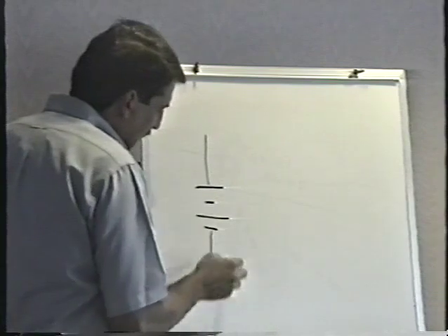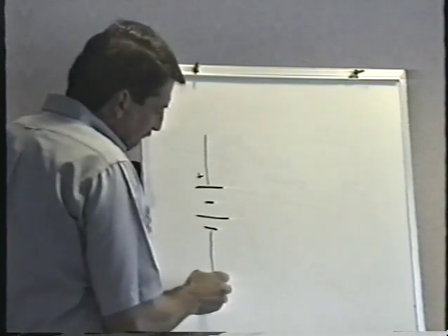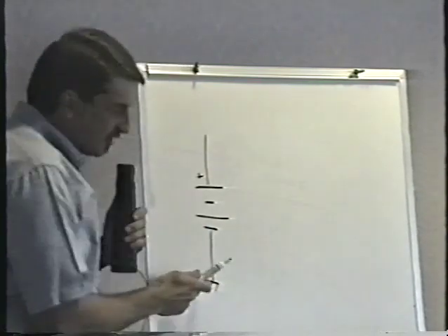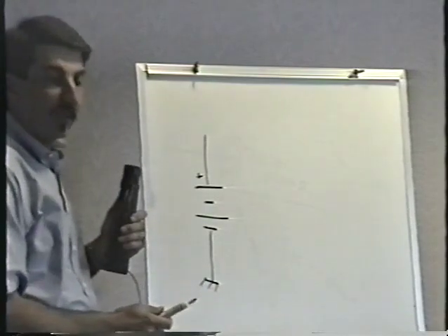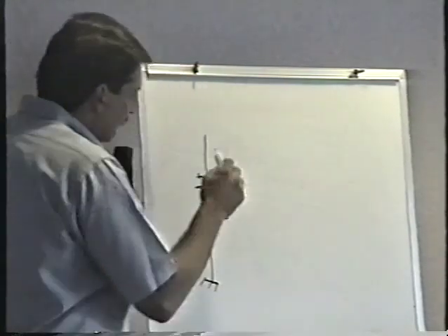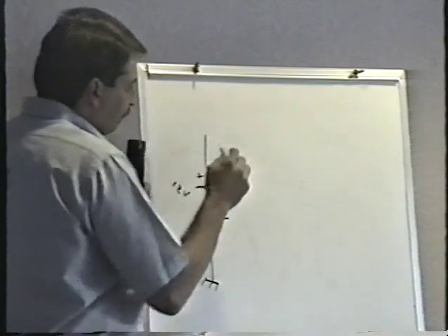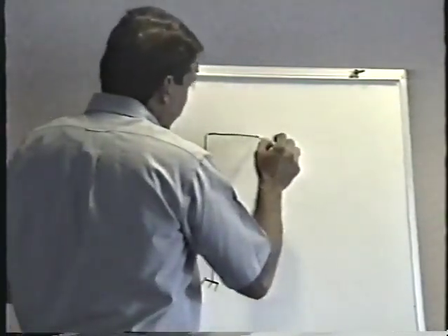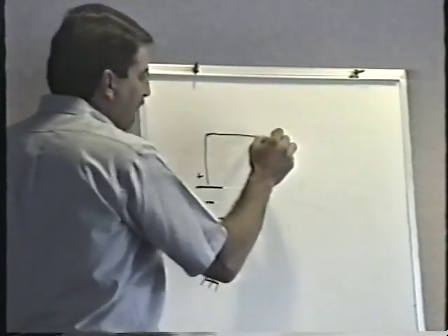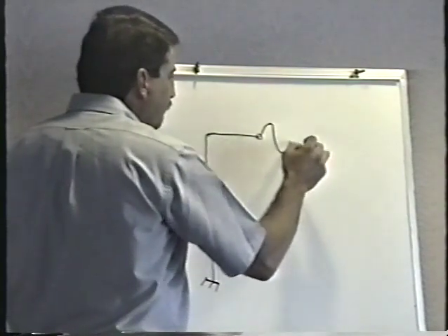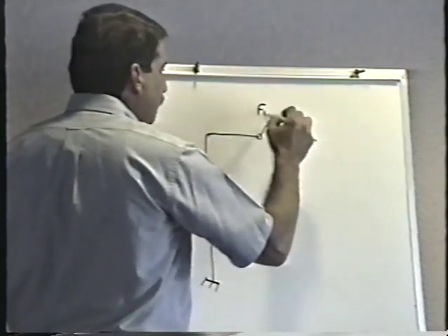So here's our car battery and negative ground. And remember, that's that chassis ground symbol that we looked at yesterday. And it's a 12-volt car battery. And the current would leave the battery, and presumably it would go through a fuse first. And this is the schematic symbol for a fuse.